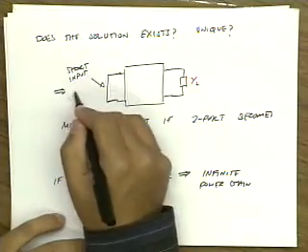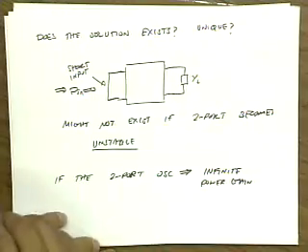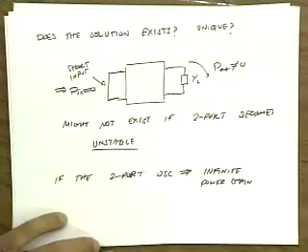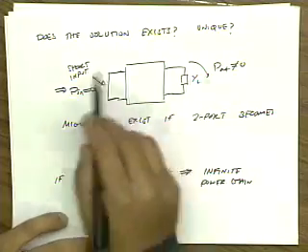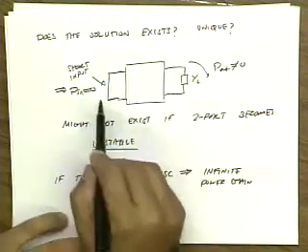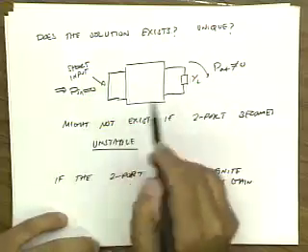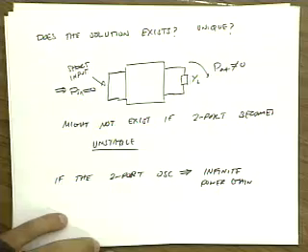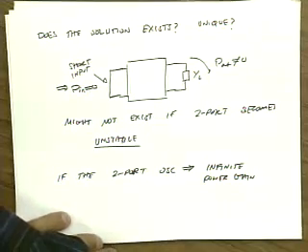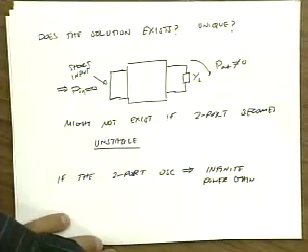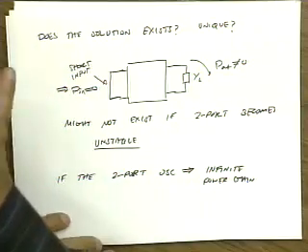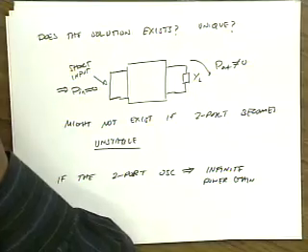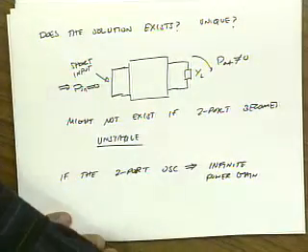So that means that Pin is equal to 0, and yet I could have Pout not equal to 0. That means that the two ports are actually oscillating and in effect generating infinite power gain. So when we derive the expressions for GT max, we'll actually find a mathematical condition that has to be satisfied, and we'll show later on that this condition is equivalent to the condition for stability.